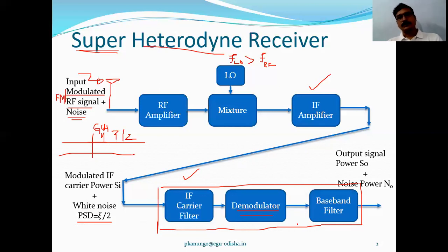It blocks, because it is known as a baseband filter, because it also blocks the DC component as well as the higher order harmonics, and any frequency component beyond my message signal bandwidth will be suppressed by this baseband filter. So the input to this receiver, if you look at it, is basically the modulated IF carrier signal, that is now here at the input to the receiver.